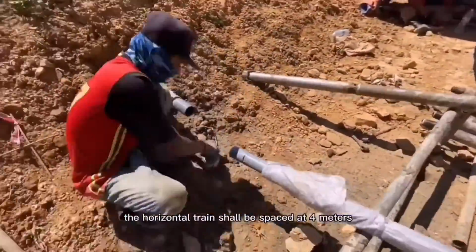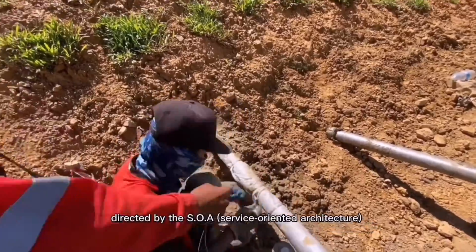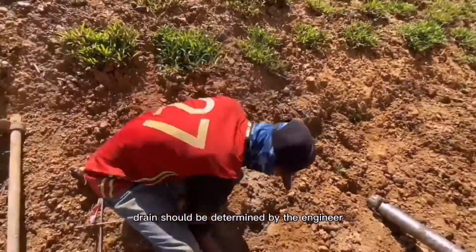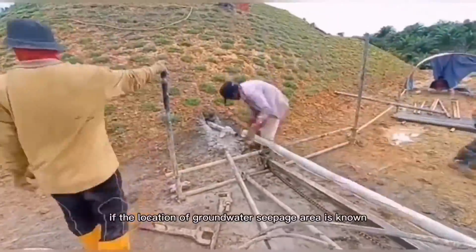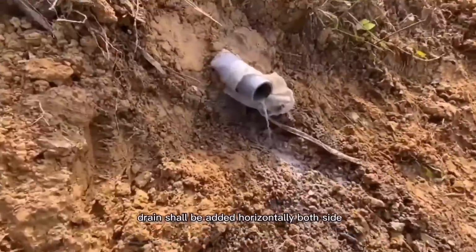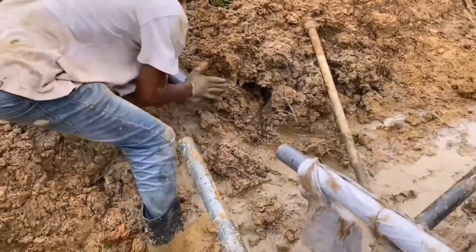The horizontal drain should be spaced at 4 meters center to center or as directed by the SOA. The location of the horizontal drain should be determined by the engineer on site if the exact location of groundwater seepage is known. If the location of the groundwater seepage area is known, horizontal drains should be added horizontally on both sides until there is no water coming out from the last one installed.